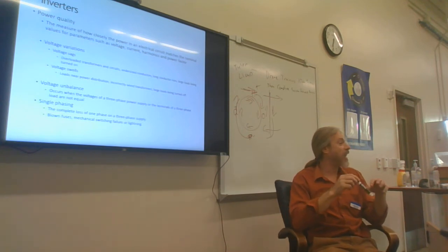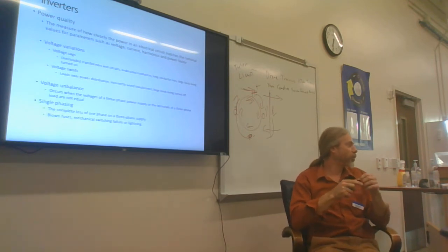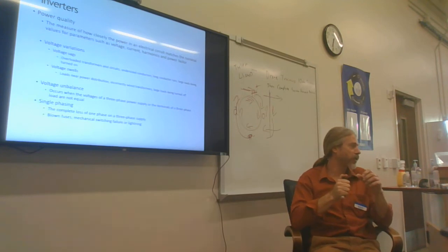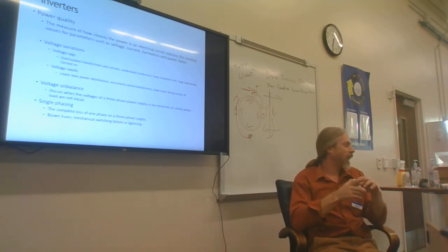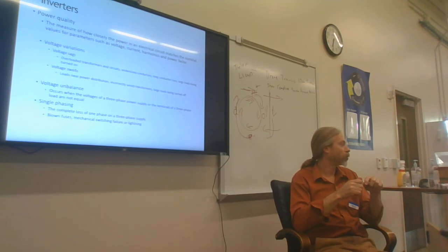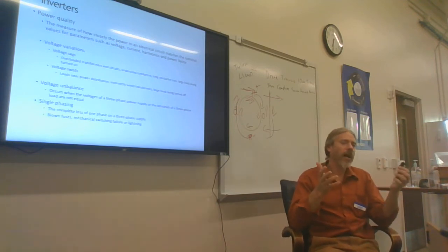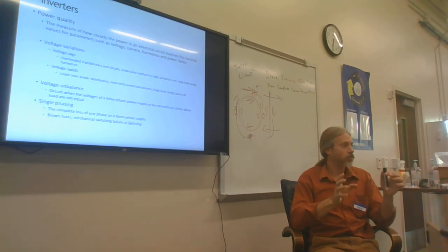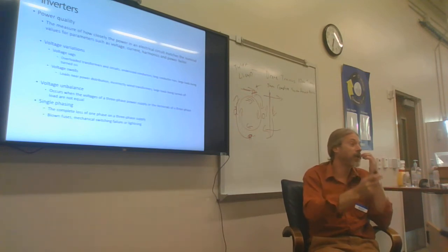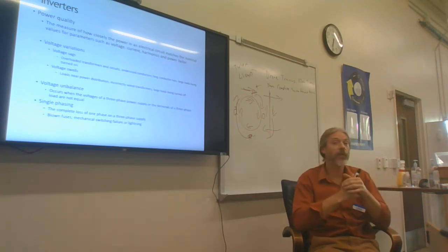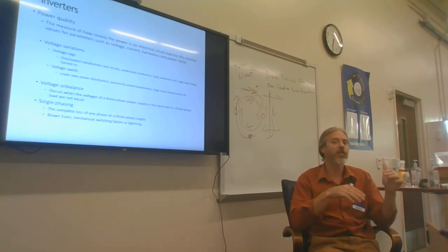Voltage sags and swells. Voltage sags overload transformers and circuits. They cause problems for long conductor runs. Why? Well, your loads need a certain amount of wattage, not just current. Say I've got a refrigerator that needs 1500 watts, and a 14 gauge wire running to it. Suddenly the voltage sags, and instead of 120 volt AC, it's now 90 volt AC.